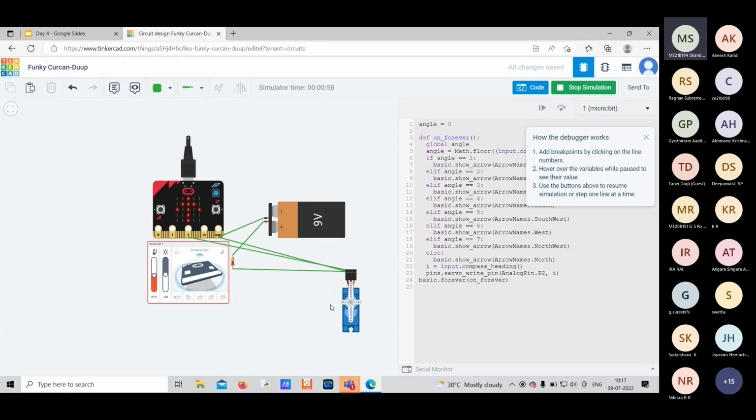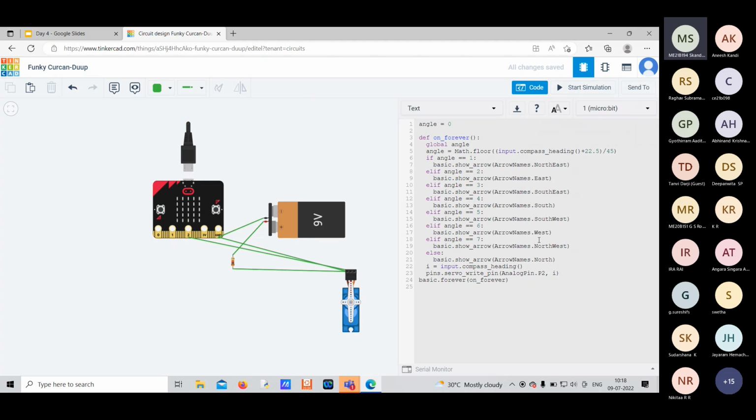And that too, the basic functionality available with your servo motor is that it can rotate only between the angles of 0 to 180. So what I'm going to do is change the code very slightly, in a way that it is able to mimic the directional change, at least for 180 first. And then I'll change the code once again so that the other side of your pointer will point in the direction that is required. Let me show it through the code rather than saying it in words. Until 180, it has to move in the opposite direction than our favorable direction.